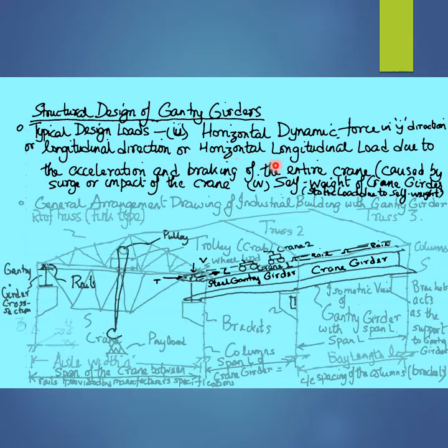The characteristic of the horizontal dynamic longitudinal load acting in the longitudinal y direction is conceptually different from the horizontal dynamic transverse load acting in the x direction that was discussed in the previous slide.